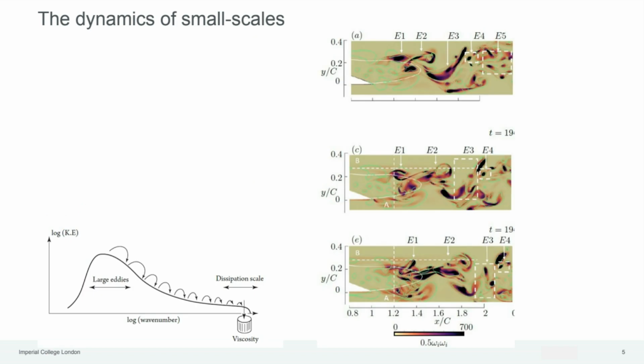And basically the basic cartoon of the vortex cascade is that we want to conserve momentum, and as we stretch the vortex, the cross-section will get smaller and smaller until it's small enough that viscosity can act on it and dissipate. That's the basic idea of the turbulence cascade.